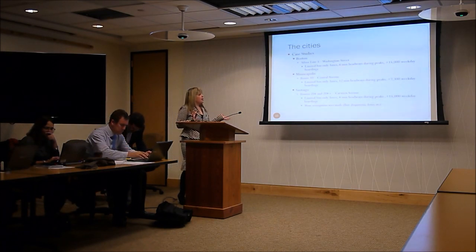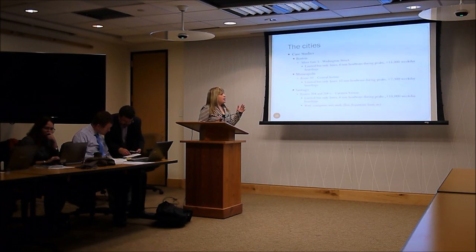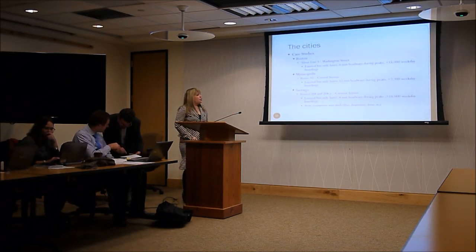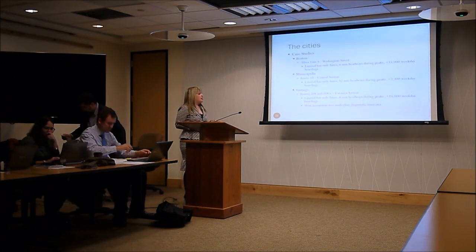These are three very interesting corridors because they're different in headways. One has 4 minute headways on the peaks, another has 12, and on the ridership, for example, Central Avenue has 7,000 weekday boardings, but the others have about double that. So I'm looking at different demands and different headways to get more insight into what the best strategy is.